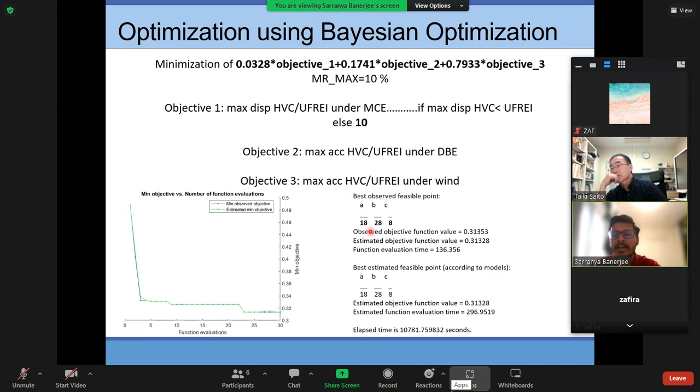Now the results show that we need around 18% of the mass ratio for the earthquake case at the base floor, and the rest for the wind case. So this is some minimum mass ratio that is required, tuned to the earthquake, so that the base displacement doesn't exceed the base displacement of only the isolated structure.